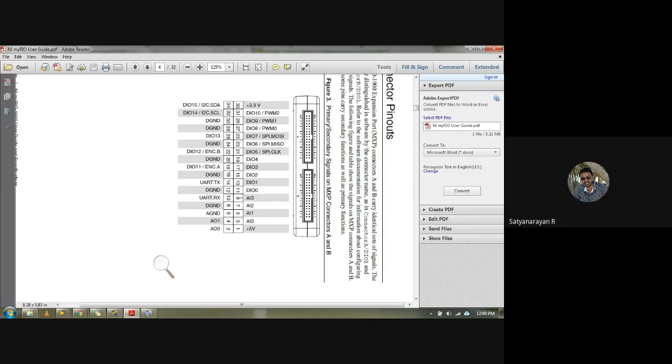I told you that whenever you are trying to connect your sensor, I connected the IR sensor and was showing you the demo, make sure that you connect for positive as well as negative. Negative has to be properly grounded, otherwise you will not get the proper output. I even showed you a demo, right? The same way here, it is not connected as a differential port, since it is single-ended. Means on the board itself they have given all the negative connections as a common ground. So here there is no need to give the common ground for each and every terminal. Instead you can directly connect your input and check your output back.